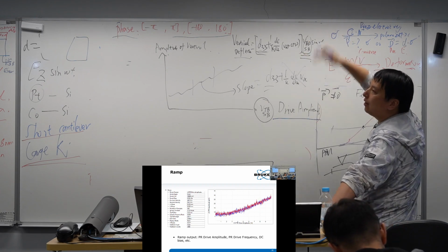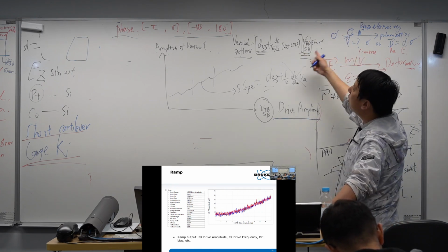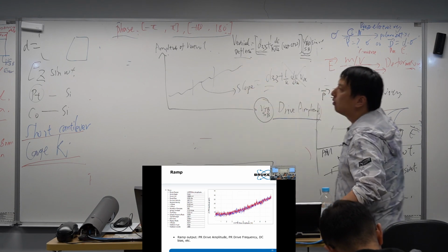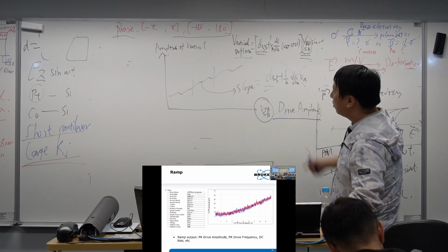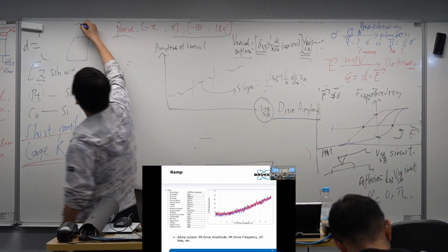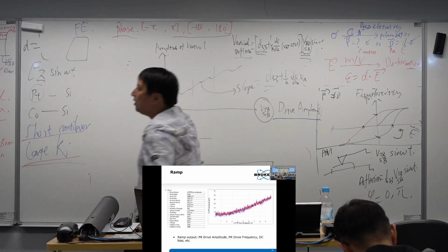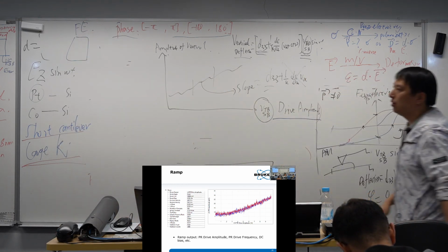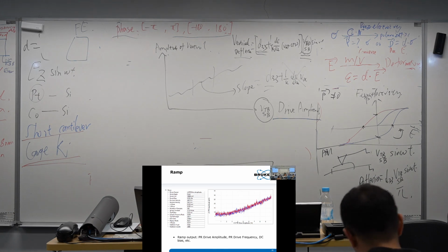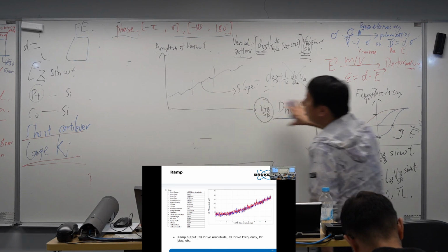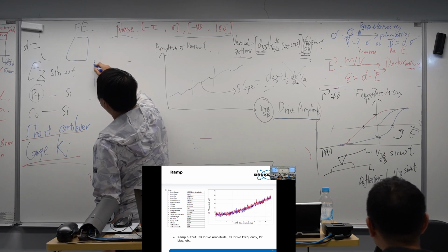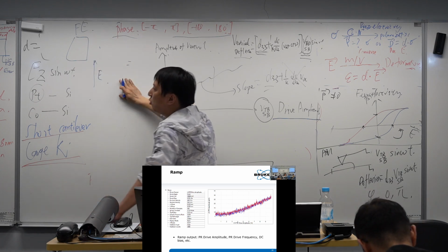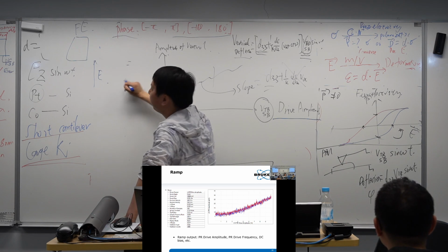We just apply an electric field because we want to detect the piezo effect. But we are studying ferroelectric materials. Inside ferroelectric materials, there is a property called coercivity. So when we do it, we don't want our electric field to exceed the coercivity, right?